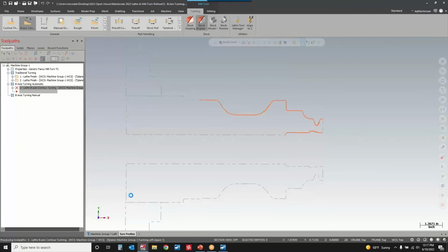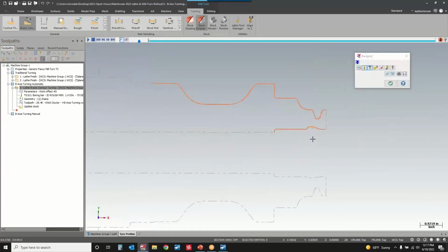toolpath's going to be good, but it could be better. Problem is we might see that our tool holder rubs a little bit on our ID. Not so good. So I want to take a look at that and how we end up editing this. So as our tool comes into play here, we're going to see that we're going to get a little bit of rubbing here, and it doesn't get in all the way. So that's not so good. Let's address finishing this toolpath up.